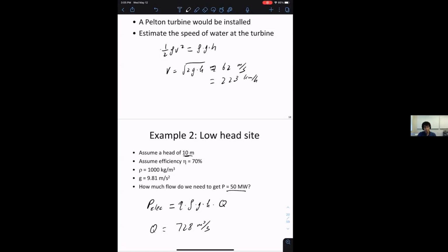So I understand obviously why you wouldn't want low, but are there any situations where it's high? So high volume. High we have, but high normally turns out to be more efficient to have many turbines instead of a few large ones. So the best place is high head, high volume. Then what we do is we have a lot of turbines. It's more efficient to build many than some super large turbines. So if you have high height, then we have many penstocks, and you have say 20 turbines in parallel. That's a more common situation.